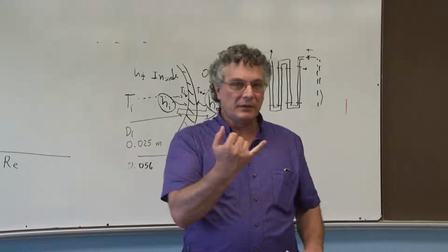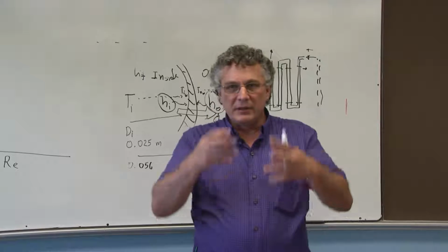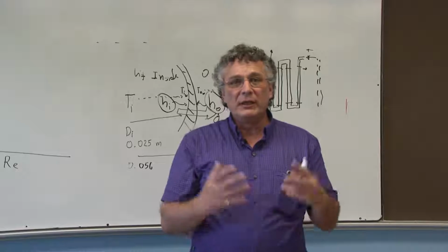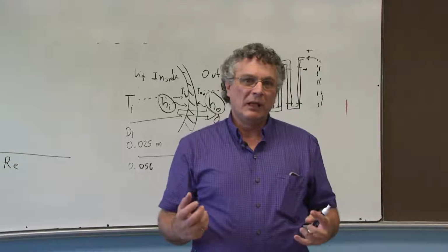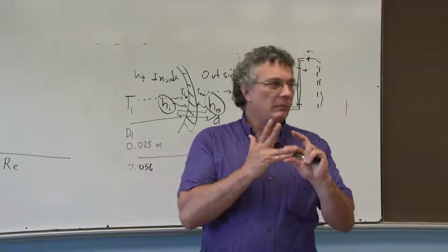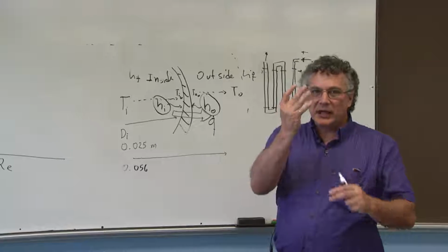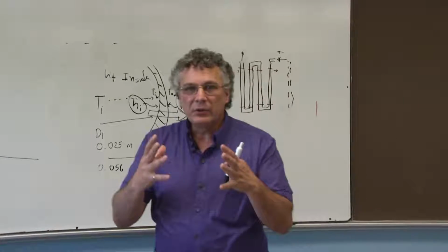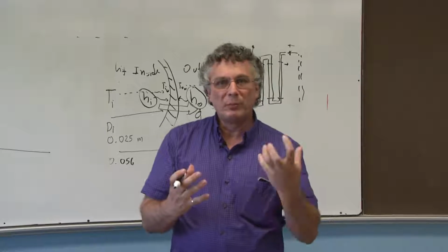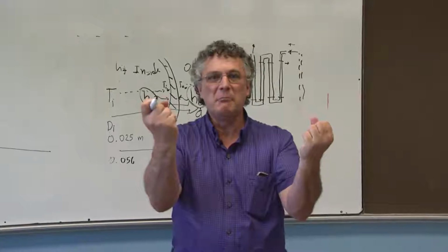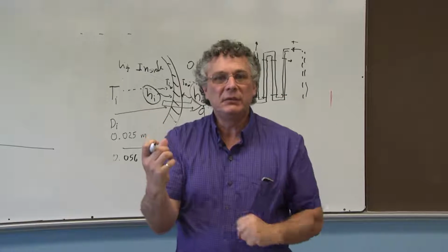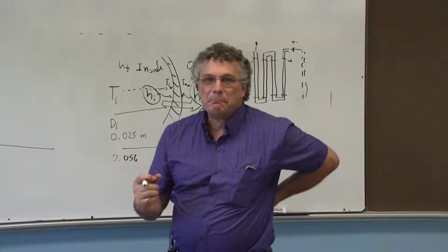So, number one, characteristics of the fluids. Number two, geometrical and materials characteristics of the heat exchanger. Number three, operational regime. Do we have large flow rates, small flow rates? All those can be changed without changing the previous ones. So we have those three types of characteristics that we need to use to predict the behavior. Since the lab wants to predict a behavior and compare it to a measured experimental behavior, what we need is to remind you of these predictive tools that you learned in your heat transfer class.